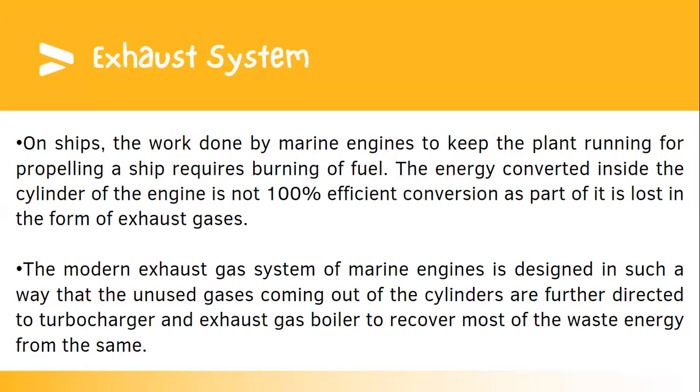On ships, the work done by marine engines to keep the plant running for propelling a ship requires burning of fuel. The energy converted inside the cylinder of the engine is not 100% efficient. Part of it is lost in the form of exhaust gases. The modern exhaust gas system of a marine engine is designed in such a way that unused gases coming out of the cylinders are further directed to the turbocharger and an exhaust gas boiler to recover most of the waste energy from the same.